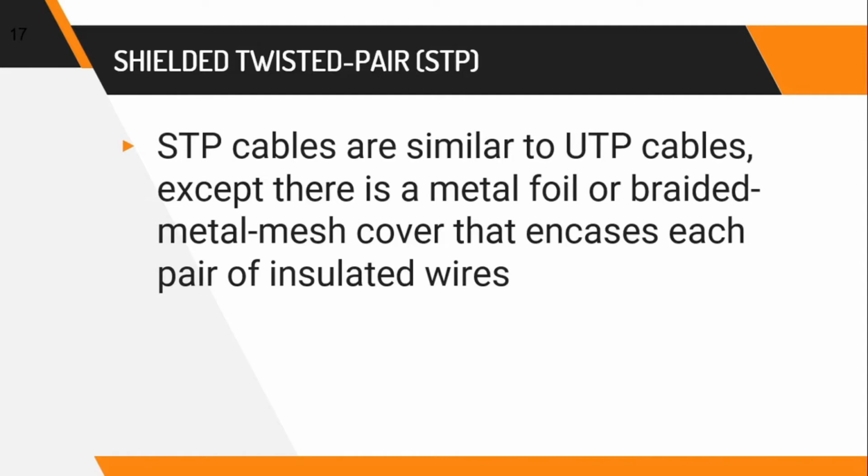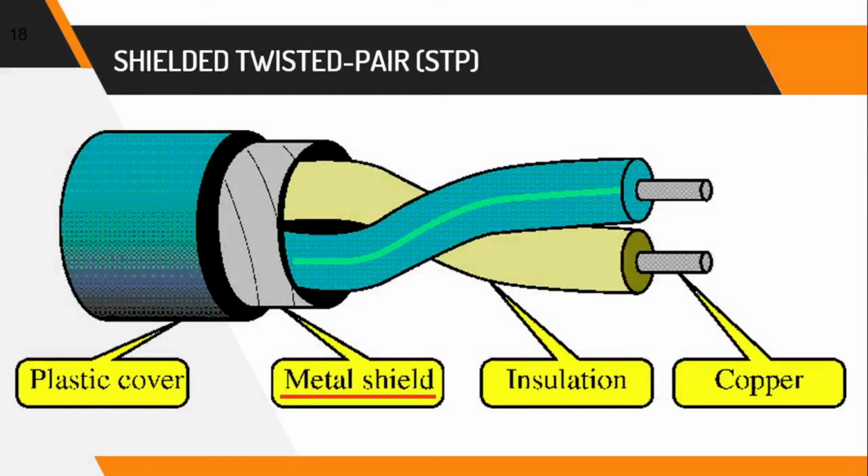Shielded twisted pair cable encases the signal carrying wires in a conducting shield as a means of reducing the potential for electromagnetic interference. How effective the shielding is depends on the material used for the shield, its thickness and frequency, the type of electromagnetic noise field, the distance from the noise source to the shield, any shield discontinuity, and the grounding practices. So STP has the individual pairs of wires wrapped in foil, which are then wrapped again for double protection.